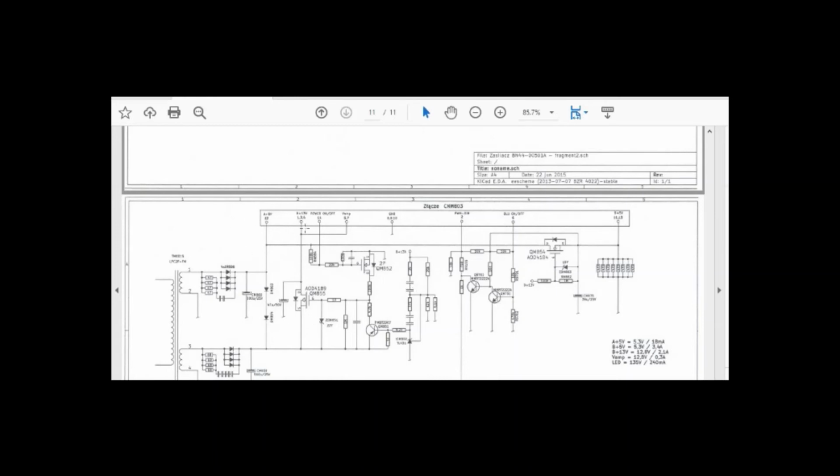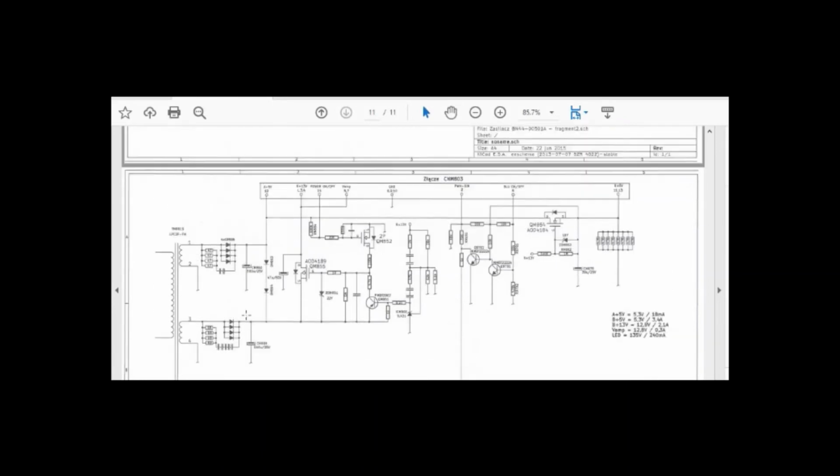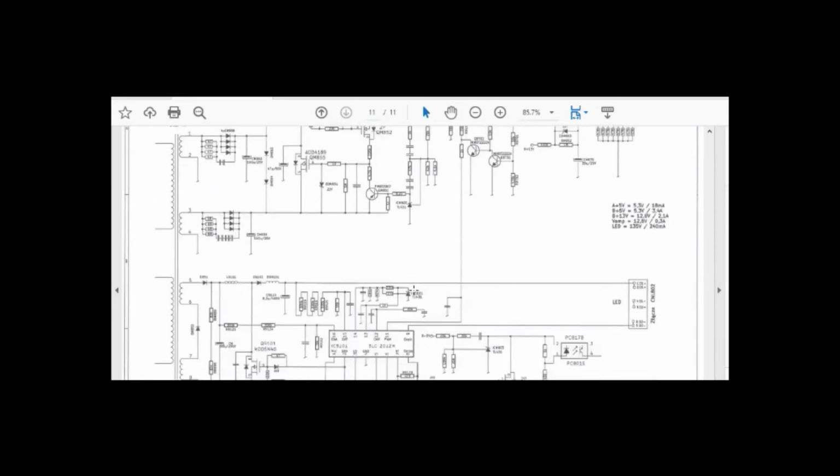And these are the set of connectors I was explaining earlier, but this is not the exact match, only a cross match. 12 volt outputs and 13 volt outputs are there. From the secondary side, it takes the outputs to two sets of surface mounted MOSFETs, and those get operated and produce the stabilized output.